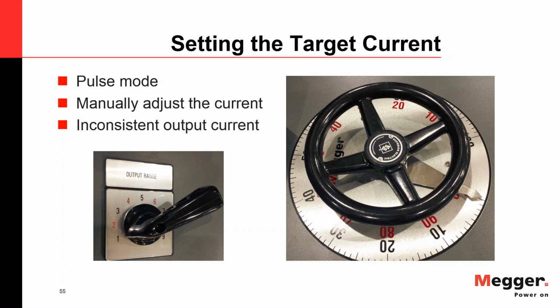The way you use that equipment specifically for long time and instantaneous testing is you put the unit into what's called the pulse mode, so it's just injecting a few cycles of current so you don't heat up the breaker, and then you find the settings for your long time test. You put the unit into the maintain mode, so it's outputting continuous current, and you run your test.